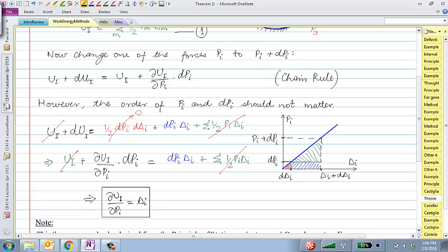So both of these theorems rely upon these thought experiments by just taking a different set of sequences of loading up the structure and measuring the change in energy when we do that. One of the theorems allows us to find unknown internal forces or unknown reactions. The second theorem is what we are going to use a lot more to find unknown displacements. Okay. As a side note,